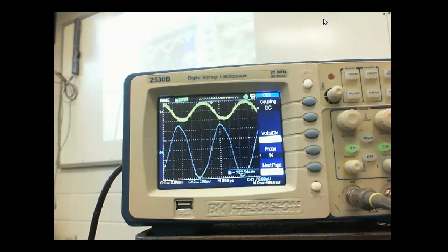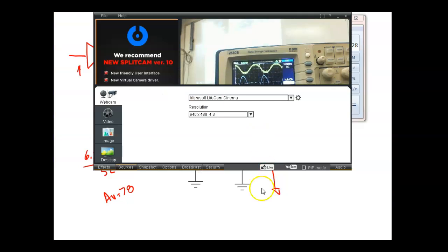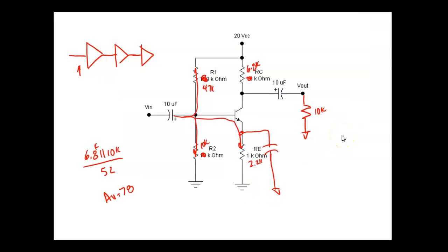So let's compute Rn. For this transistor we're going to assume a beta of 100. Would that difference not be super alarming? Not for this one. You remember sometimes you compute and then you measure and see something different and you know it's wrong. With the 77 to 56, that wide gap is not too alarming. Okay, so that's good.